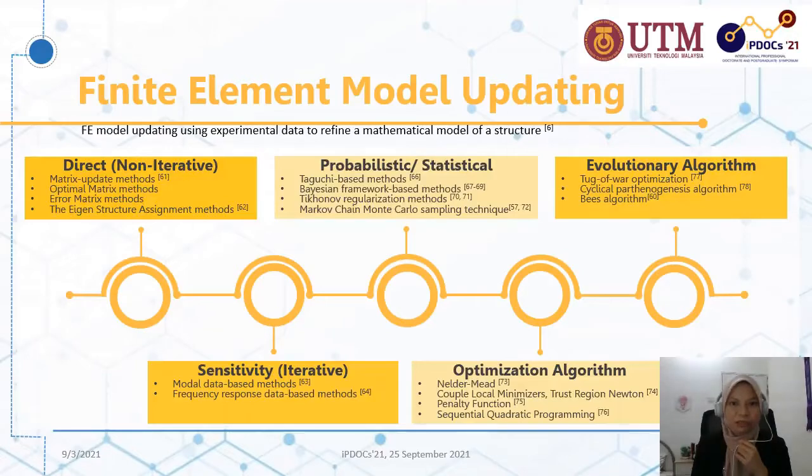Model updating can also be done by using statistical and probability-based approach. Bayesian framework-based method, Taguchi-based method, and Tikhonov regularization methods are examples of this approach. Aside from the methods mentioned earlier, researchers have examined various optimization algorithms to solve the finite element model updating problem. The optimization algorithm can be used directly or combined with the sensitivity-based method depending on the ability of the optimization algorithm to handle complex and highly nonlinear finite element model updating.